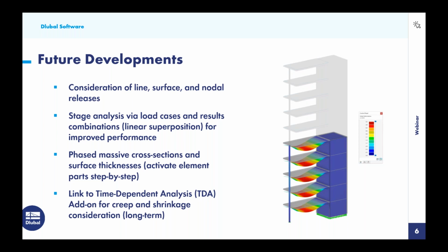So this will be extremely helpful for large models, many load combinations, rather than having to factor in these construction stages for each load combination. We can superimpose the results on the final structure to consider the stages. So this will be really helpful for just improved performance.